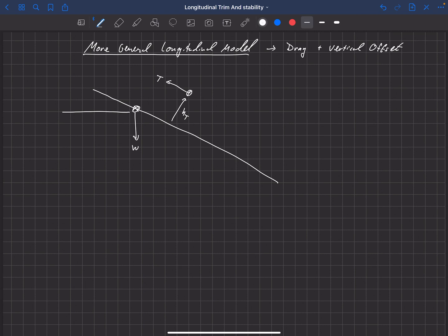we actually have three different angles that we're concerned about here. We're going to have a free stream velocity v infinity, and the angle between the fuselage reference line and v infinity is our angle of attack. The angle between v infinity and the horizontal is our climb angle, gamma, and then the summation of the two is theta. So theta equals alpha plus gamma. We are familiar with alpha and gamma from previous discussions, but theta is what's called the elevation angle.